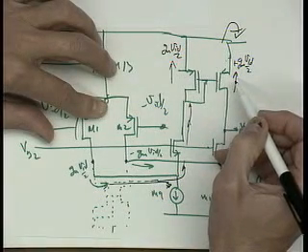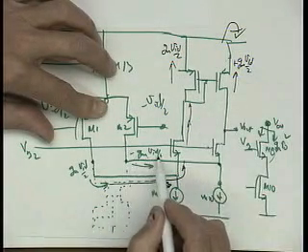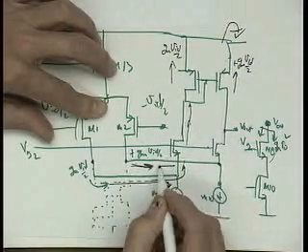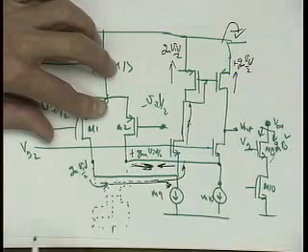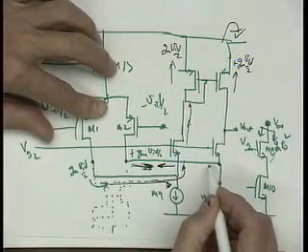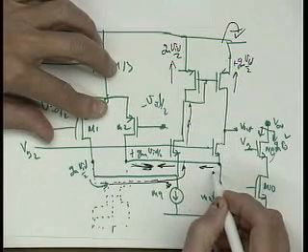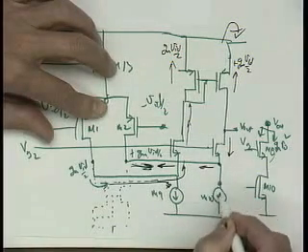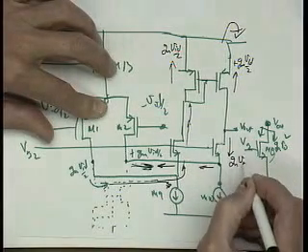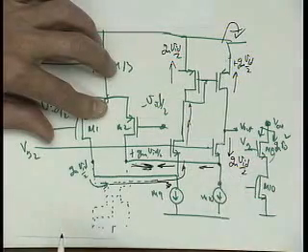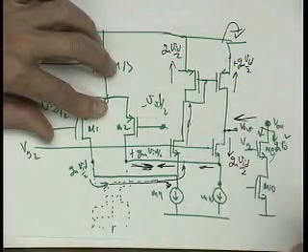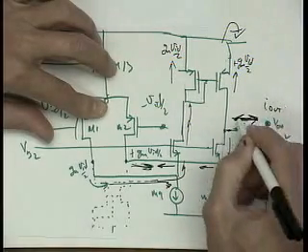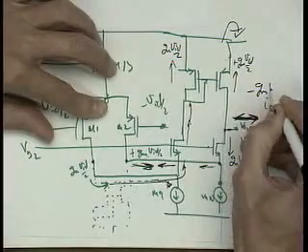Okay? What about this one? Here's minus Vn differential over 2 in this direction. So let's make it a plus Vn differential over 2, and that means it's in this direction. Okay? This goes over here, so it's going in this direction, plus Gm differential over 2. Comes up to here, it's going in this direction. Can't go down into this DC current source. So it's another Gm Vn differential over 2 coming down here. What needs to come into here? This is sort of our I out. Well, I out's generally written this way. It's going to be minus Gm Vn differential.